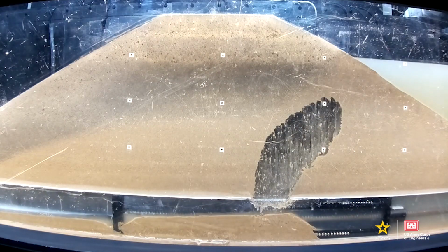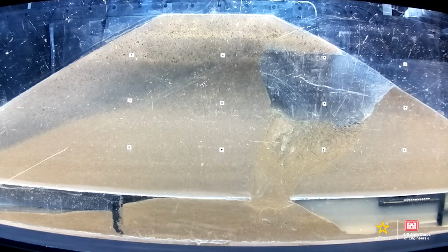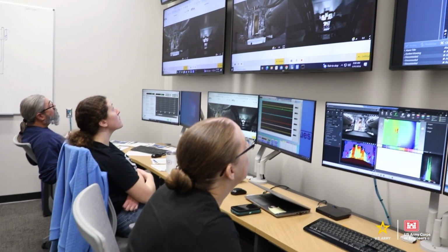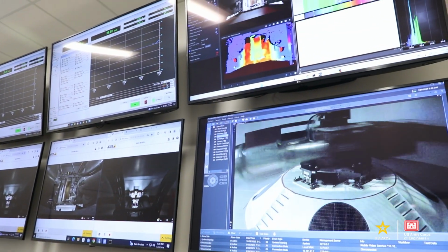And when it does that, sometimes it takes some of the fine grains of the soil with it, and so the erosion channel eventually can propagate and create total failure of the levee. Understanding this process is kind of multifold. This particular project, we really wanted to know what kind of early warning signs might there be so that we can fix a problem before it gets too extreme.